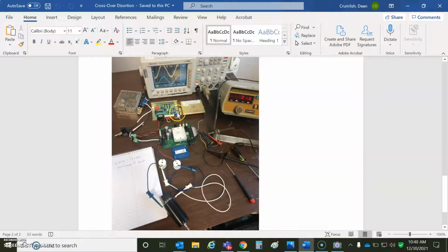So the old 4212, the 503 is a similar size. Bantam's much smaller. Again, function generators, just command and a little sine wave in, and I'm measuring the actual current monitor coming out onto channel 1. In this case, I have 2 150 microhenry inductors in series with a low inductance motor, just to get the inductance up. And I use the high gain setting.